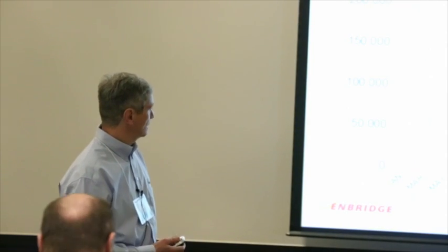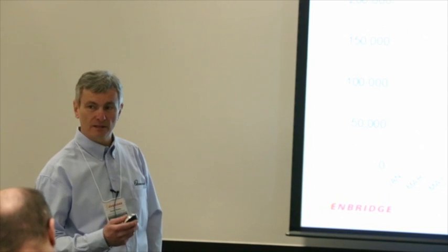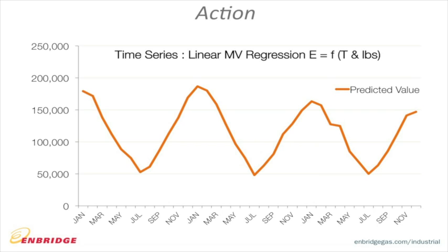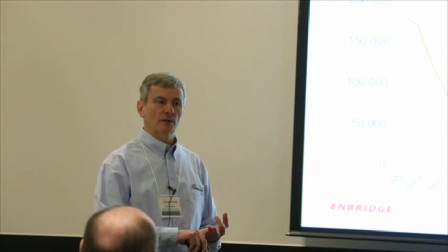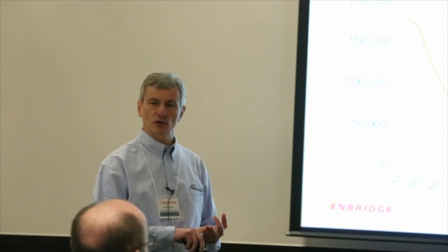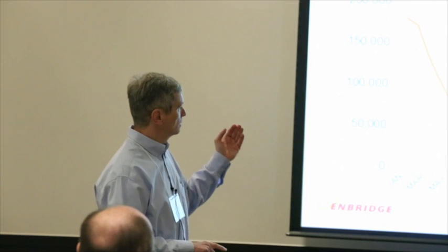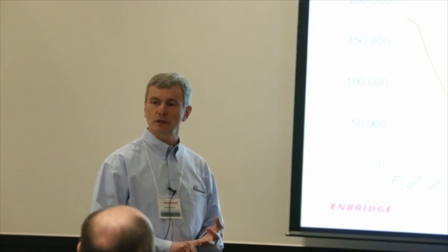And now I'm going to put these predicted values into the time series. This is what the model is telling me I should be using. You told the model, this is your outdoor temperature month by month. This is my natural gas consumption historically over 3 years. This is the level of production of those same time intervals. So if it's monthly consumption, it's monthly production intervals. This is what I think this should be using.